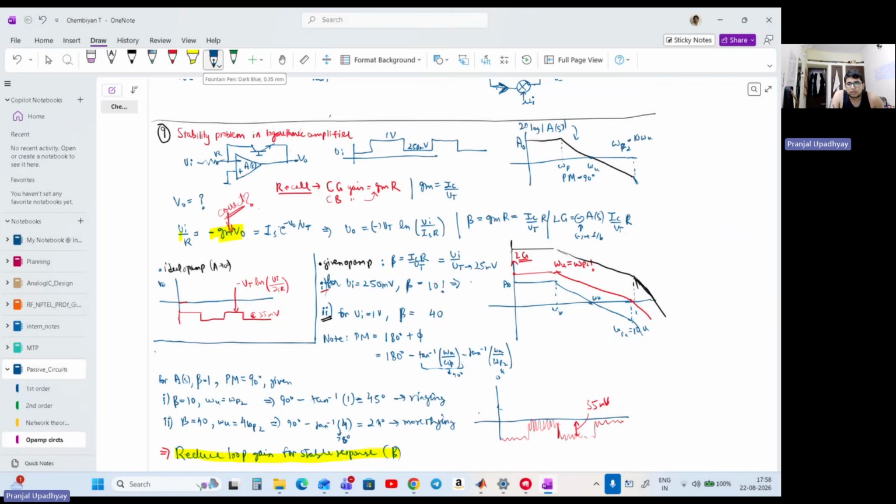The loop gain that we are writing: here we are first of all expressing our feedback factor as the voltage here and the voltage that is appearing here due to this voltage. So what you understand is that because of the application of voltage over here, we are having some voltage over here, which is basically just the gain of this BJT, right?